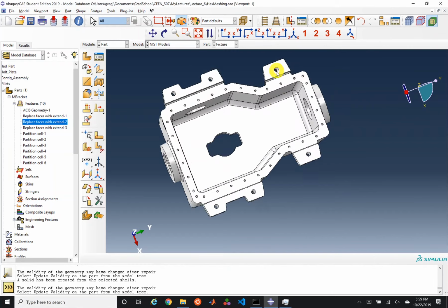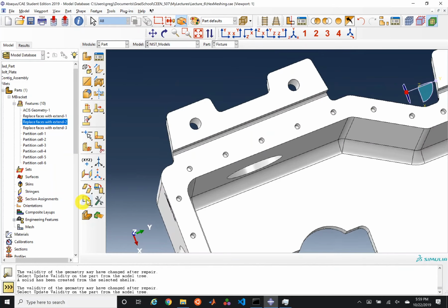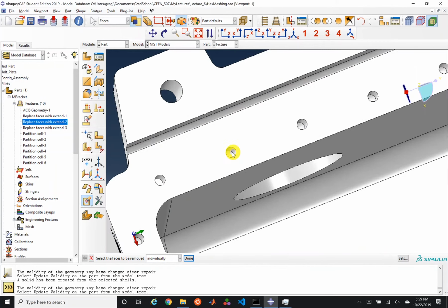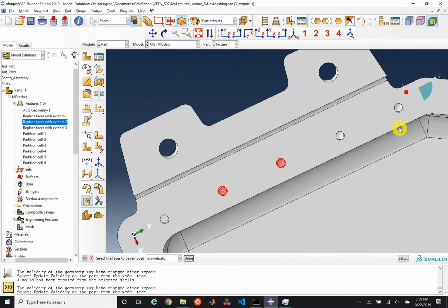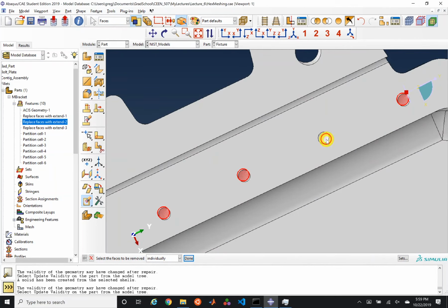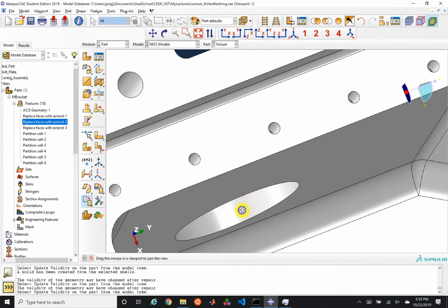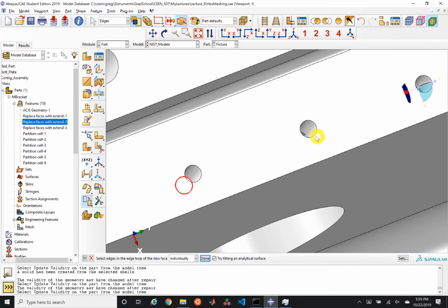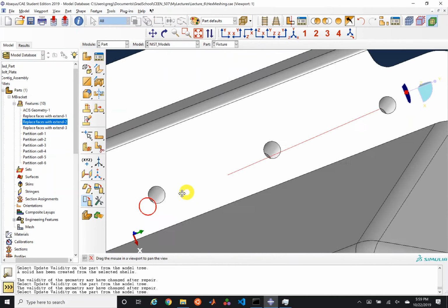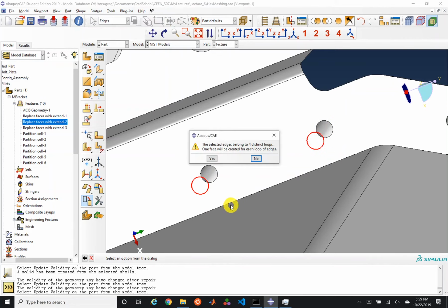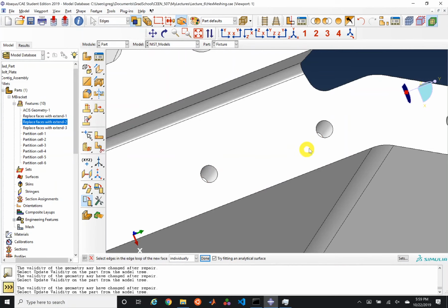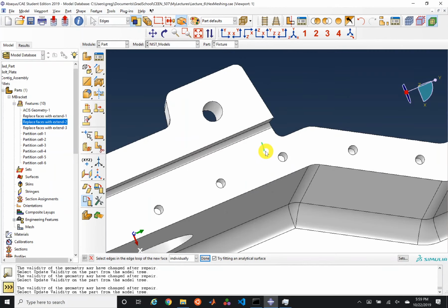And then the other part of this is that you can also remove faces multiple at a time. So instead we could have come through and literally selected all of these faces. I'll only do 4 here. And then we could cover edges for just these 4. So we could shift select through all of these, control to unselect, and then it'll tell us it's going to create 4 distinct loops. So it created 4 faces. So that's how you can batch process those.